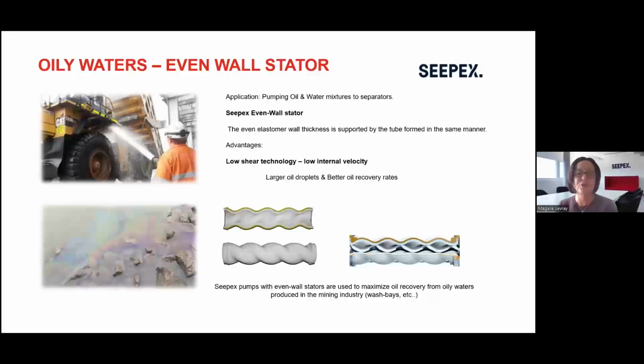So we have low internal velocity, and that enables us to recover larger oil droplets and indeed better oil recovery rates.